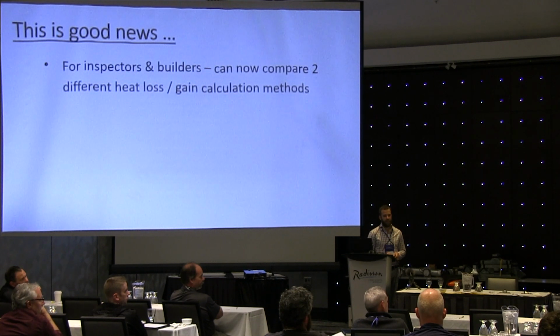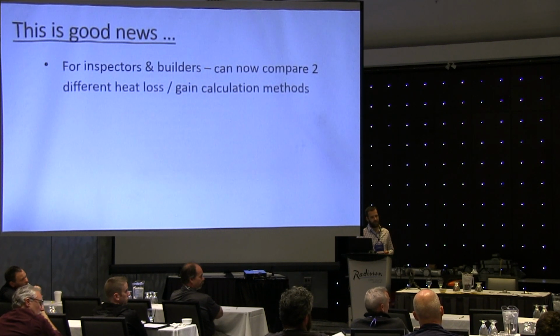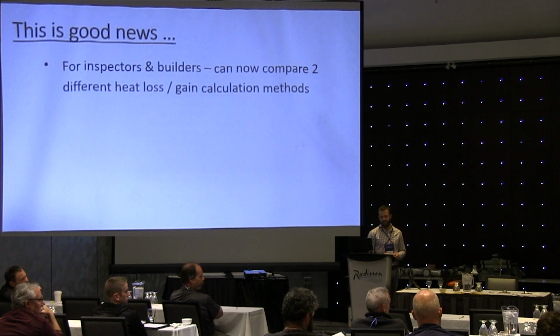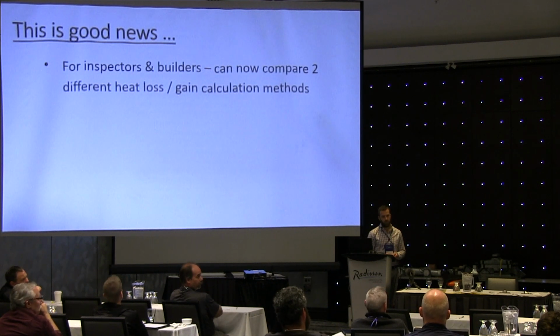Yeah. That's the kind of stuff we're trying to correct. The analogy I use is when you're driving a car, if you have a 400 horsepower engine in a Volkswagen, you've got two positions for the throttle, wide open or nothing. It's a poor ride. But if you get something that's closer to load, even though you may forfeit a little bit of pickup, you're going to give a lot finer comfort in the shoulder seasons, which constitute most of the heating season. I don't disagree.